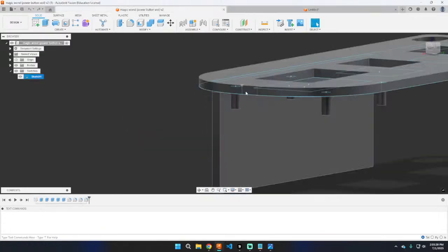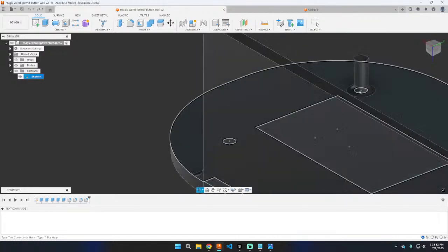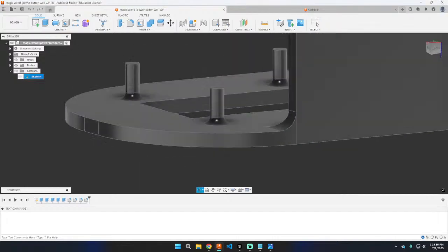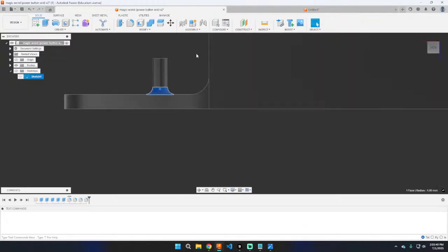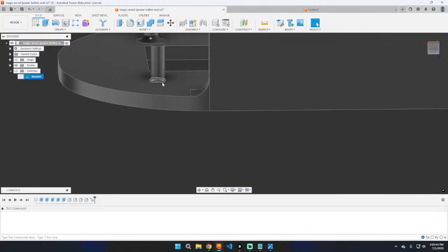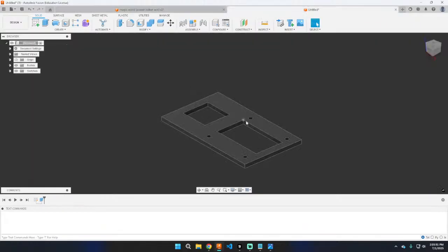And the posts that I'm wanting to use here. Okay, I have a fillet to kind of round it out. Here, I'll hide the sketch so you can see better. You see, it kind of rounds it out to make the posts stronger. But if I remove it, we can see if we extrude it from the point, like the bottom, all it is is a 5 millimeter post.